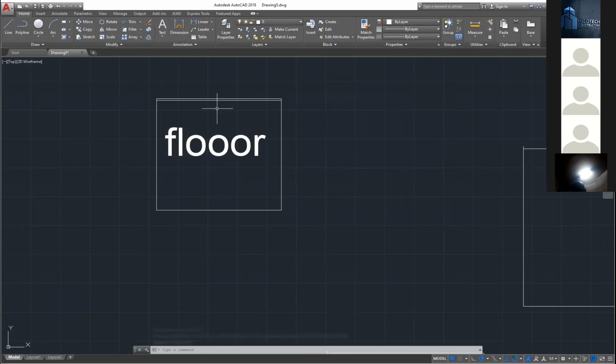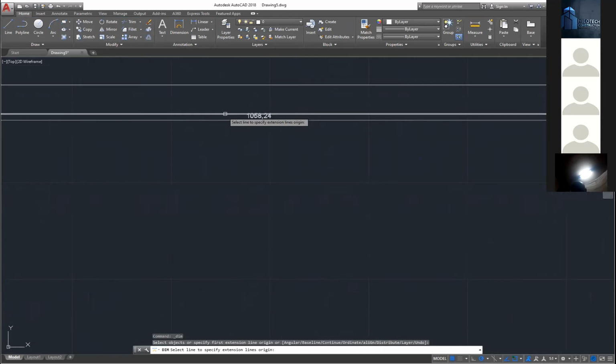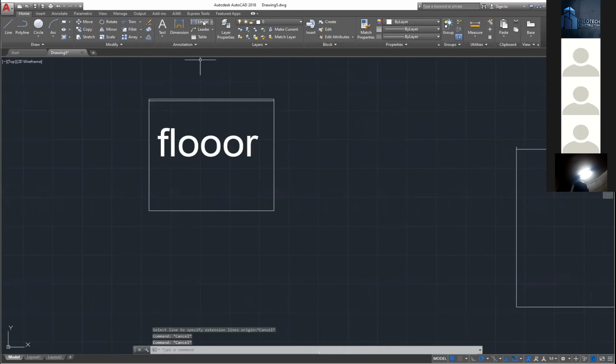Dimensioning is to dimension your design. The first one here is called a smart dimension. All you need to do is just click there, you hover over it, look here. You see that it's already giving the dimension of this without you actually taking it. So it's smart, okay? But you rarely use this. I will show you that you will always be using the linear dimension, and you are going to use it mixed with the continuous dimension, which I'm going to be showing you.